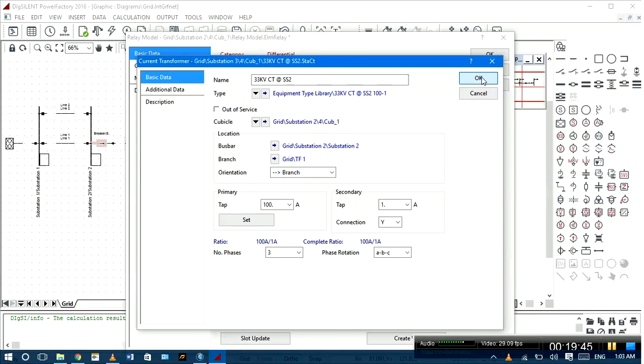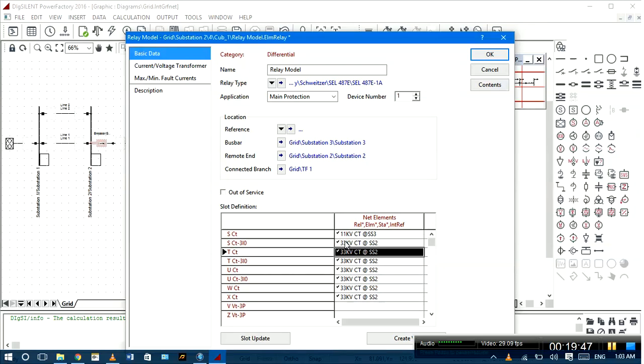Before you continue doing anything, it is very important that you make sure that these 2 windings are connected at the right places. Otherwise, your relay is not going to operate the way you want it to, and it will always be tripping even for faults that are outside of the protected zone.